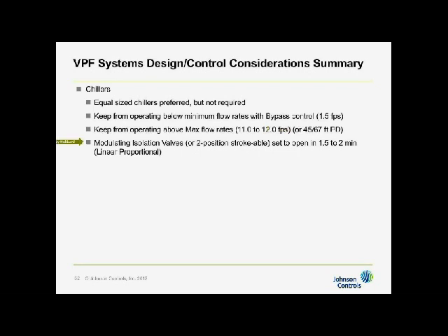Modulating isolation valves are going to be necessary. You'll see why in a few minutes, as opposed to a two-position valve. Two-position strokeable can work if it's linear. Valve position the flow. Set them to open to 1.5 to 2 minutes, linear proportion, and I'll show you an example of why that's important with a VPF system in a few minutes.